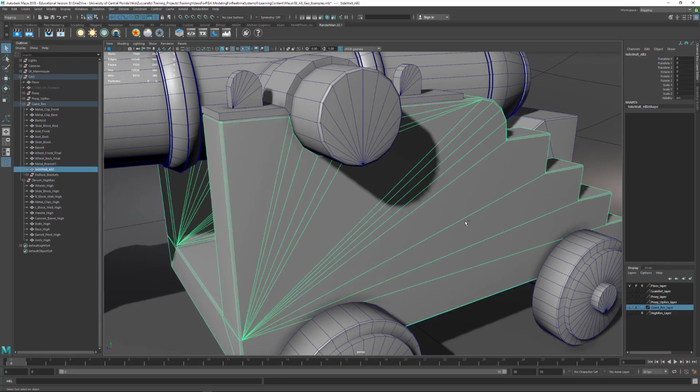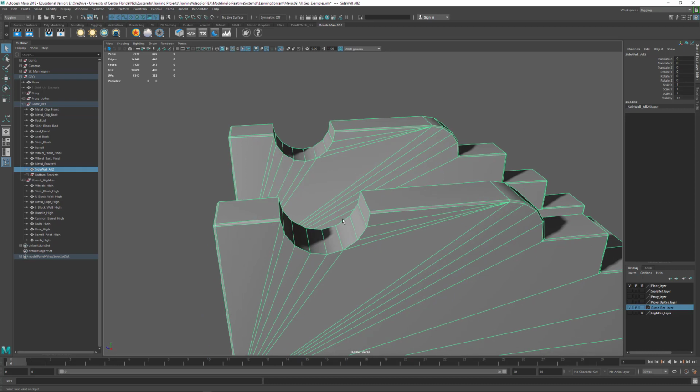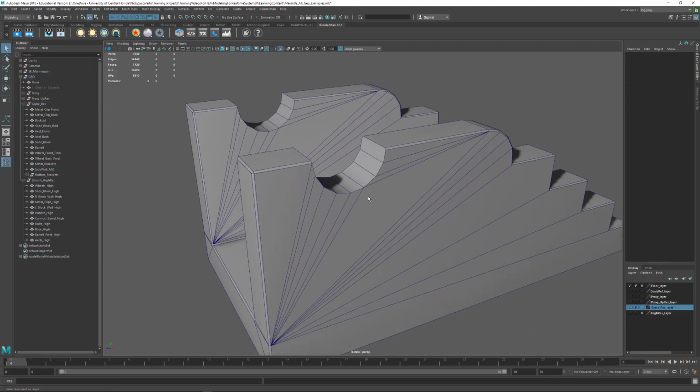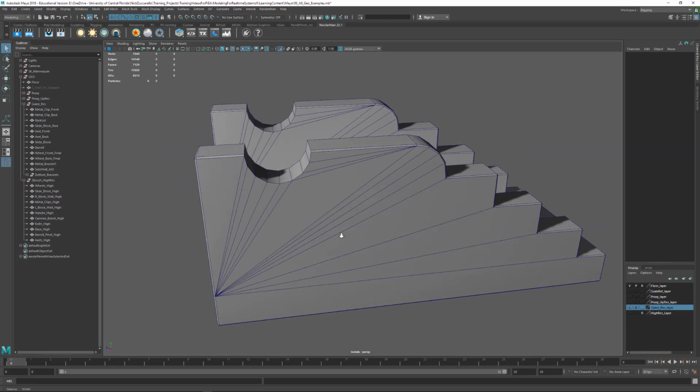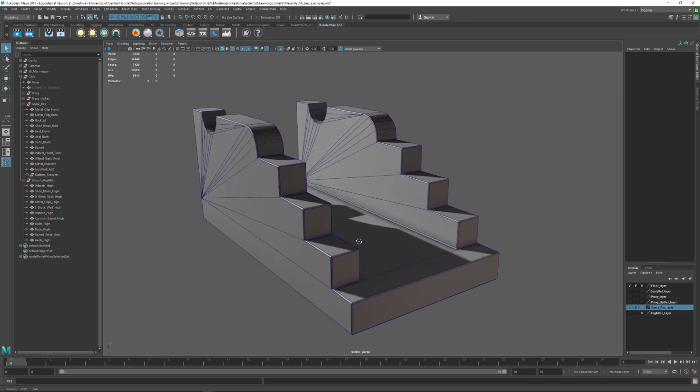Now if I hit Control 1 on here, we also took a shape that I had for that middle part, and then I did a Boolean on these things. So I ran this shape versus the cylinder that was in here. I just duplicated it and did a Boolean. So for render modeling, we can go to mesh Booleans and do a difference, and that will give you this here. I had to go and basically take the multi-cut tool and then add some splits going in specific areas, and then just use the triangulate tool to get everything in the order that it's in now.